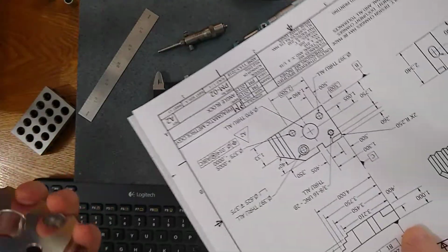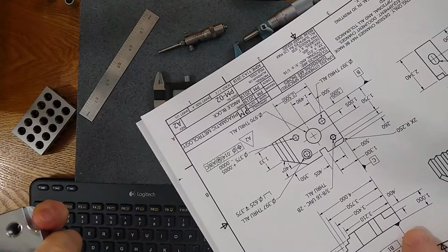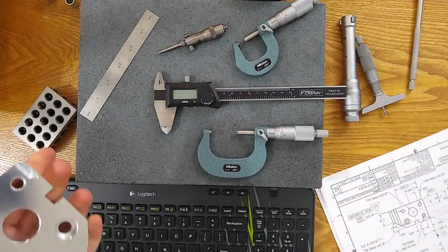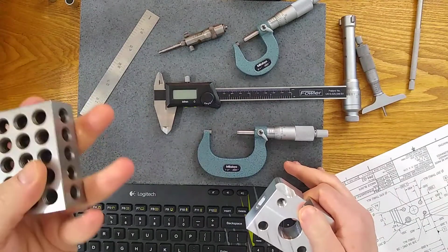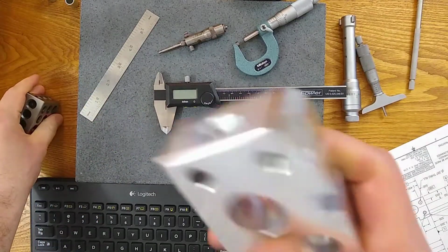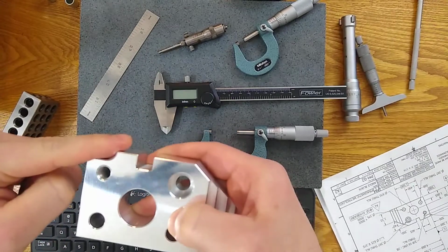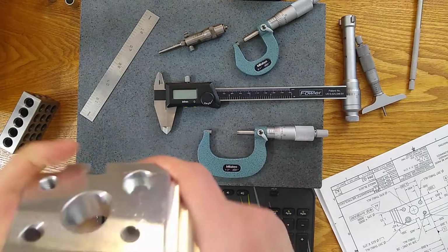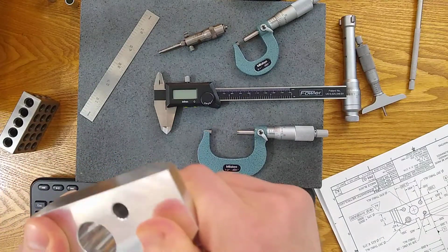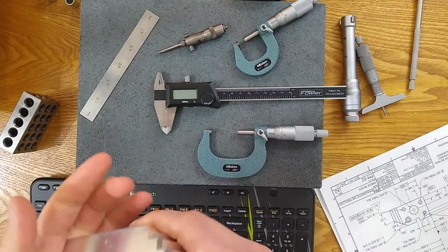But my second step, look at your part, consider how you might fixture it, consider any reference surfaces you might need. Reference surfaces could mean a granite surface, a 1, 2, 3 block, an angle block. It could also mean you need to use a reference surface from the part to get from one feature to the next. So you want to look at those, see if they're in good condition on the part, to see if they're good enough to use as references, or maybe they're still rough and unfinished, and it may not be possible.